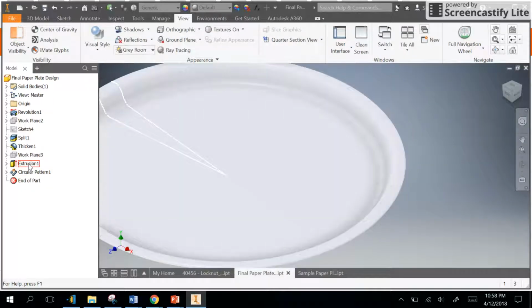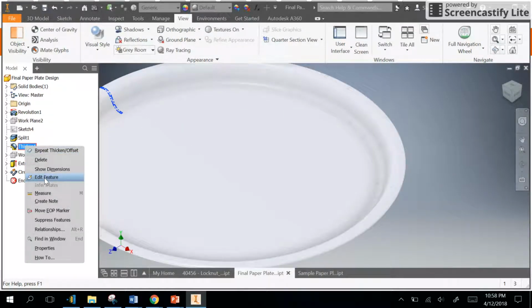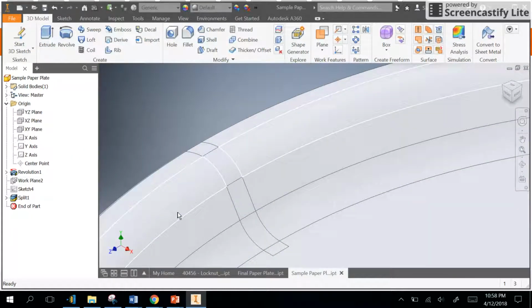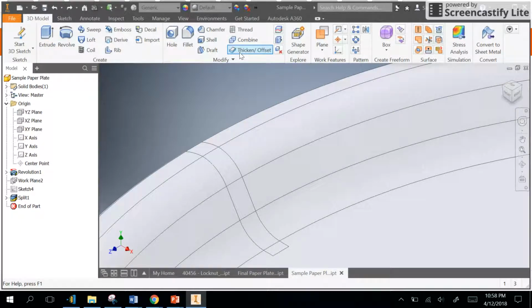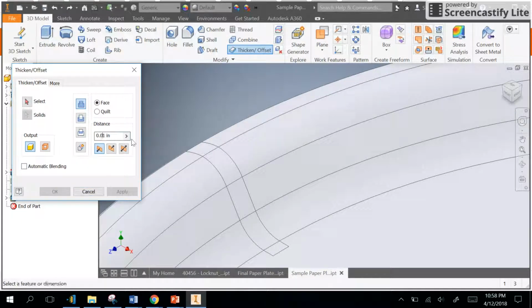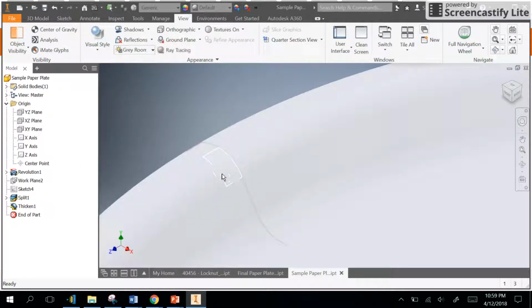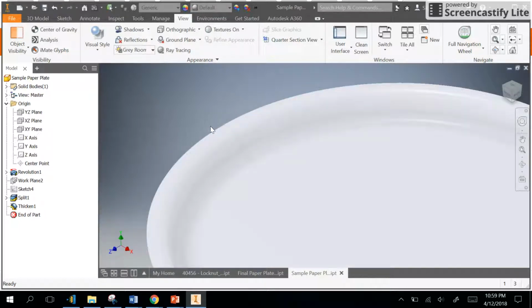Always some errors, right? What did I make the thickness of this? 0.001. Ah, no wonder. Ugh. So let me go back. I'm gonna thicken 0.01. Yeah, that makes sense. It's a pretty big difference. What do I want to thicken? These figures. I want to make it down. And I'm going to apply that. Great. Cool. Now if you go to your view and you look at it more realistic, you're going to say like, oh, okay, yeah, I see some kind of cut on it. That's cool. So most people would say like, oh, okay, great, you're almost done.